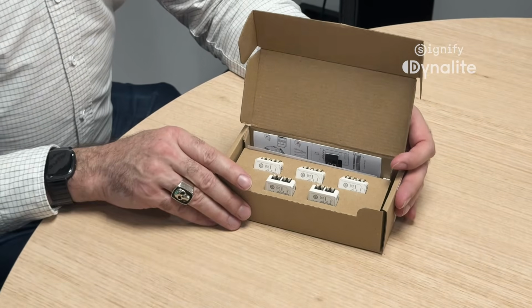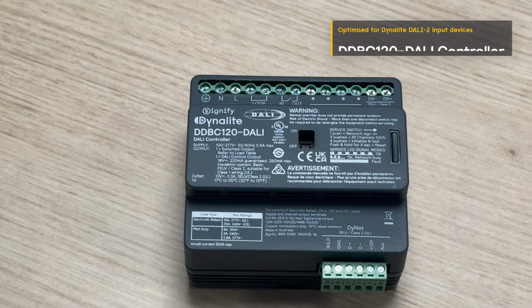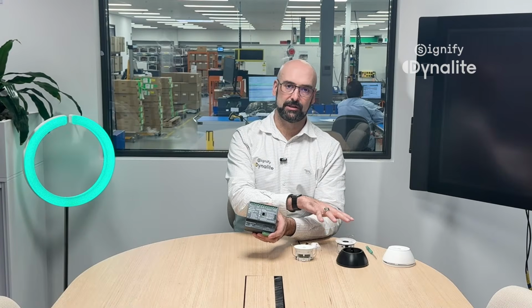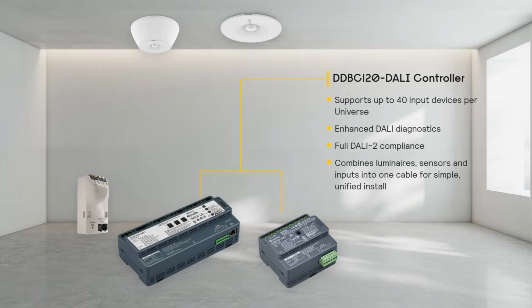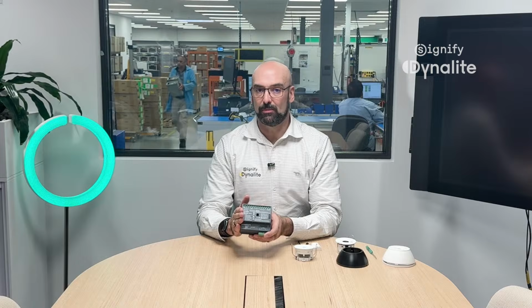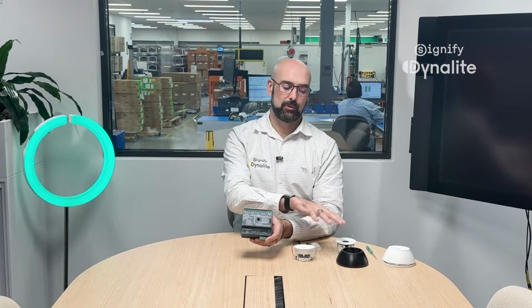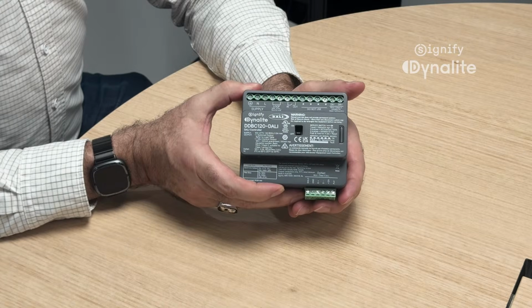These devices will be available in single units or in a cost down pack of 5. To support this, we're also updating our DDBC 120-DALI. So this is a new device, and this will allow us to be able to support the new generation of DALI controllers, as well as be backwards compatible to the existing portfolio. The existing DDBC 320-DALI, the one with the Ethernet port, will require a firmware update, which will be available on our support website. And once that firmware update has been applied, this will then support our new DALI 2 generation sensors.